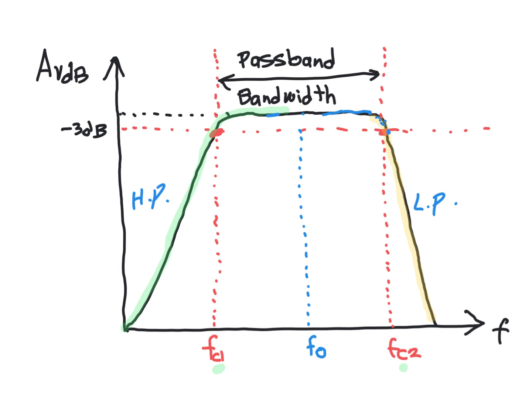If you bring back the frequency, it'll come all the way back up, keep lowering it, it'll then drop down to FC1, so you can easily experimentally determine these 2 points. That center frequency FO is like the geometric mean, the center of that waveform shape.